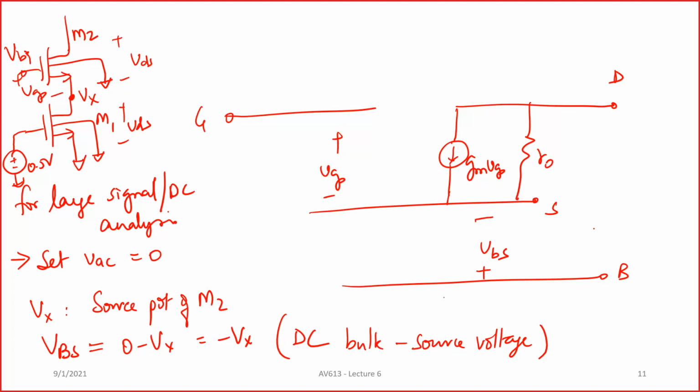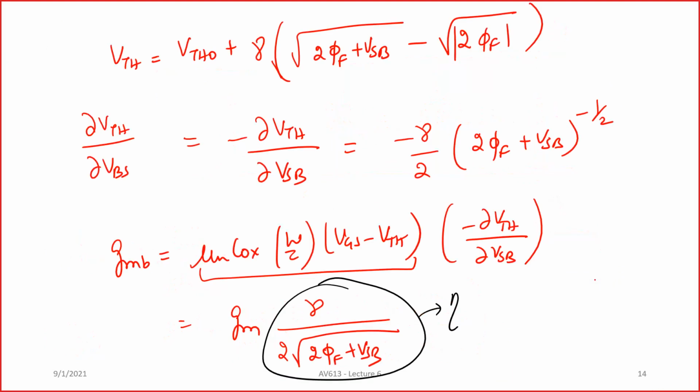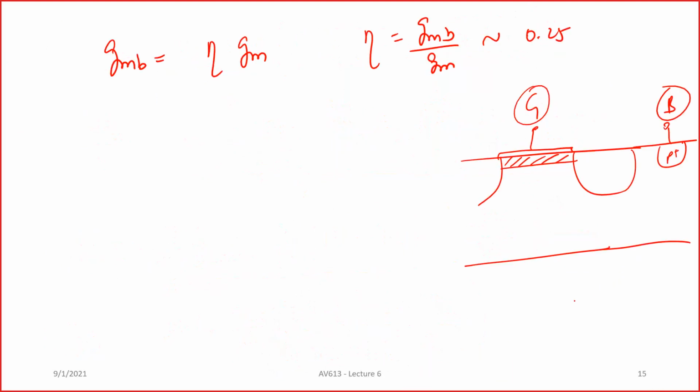Exactly, sir. As we saw in the RFIC course, it is a soft non-linearity. You don't have a dropping off a cliff kind of a response. In fact, for low frequency analog circuits, we define what is called THD. In the RFIC course, we looked at the first order compression, the third order nonlinearity, the 1 dB compression point, the two tone tests, and the intermodulation, IIP3 and things like that.